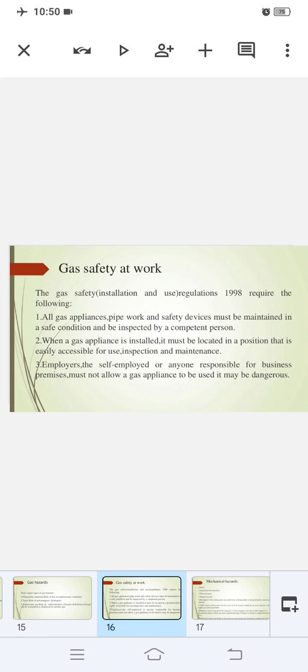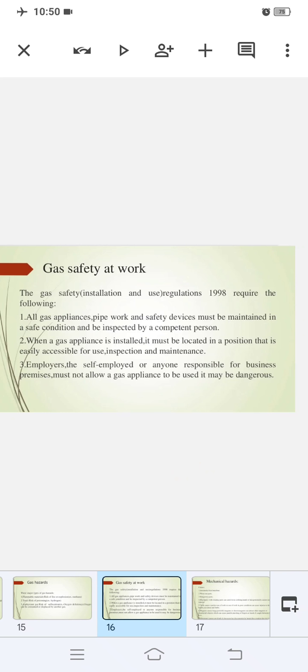And third one is electrostatic precipitators. What are electrostatic precipitators? These are fine metal wires that are stretched between tubes which are earthed. Several thousand volts of direct current is applied on the metal wires, and when the volts are supplied, a high potential difference is produced between the tubes and the wire, and that ionizes the dust particles as they pass along the air stream.